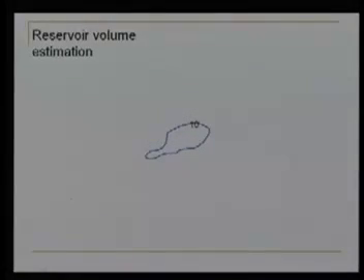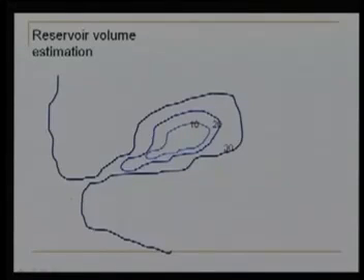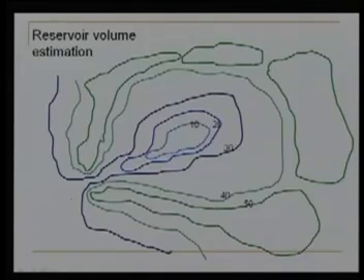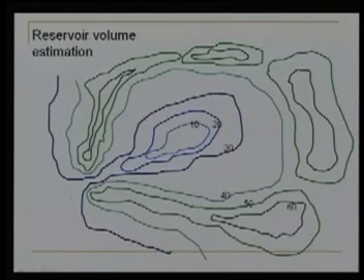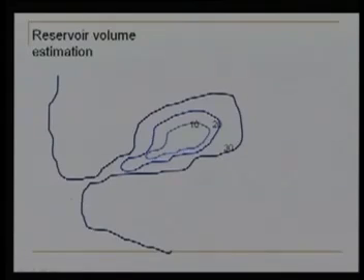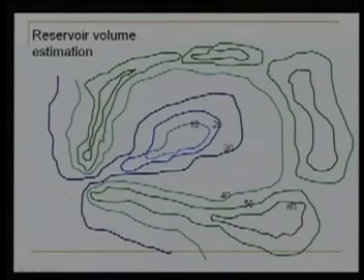Again, our area is similar to the previous case. Here we have the contours of 10 meter, 20 meter, 30 meter, then 40 meter, 50, and finally 60 meter. Now try to visualize this area the way we did with the contours before. Try to visualize what this area is like. This area is somewhat like a little valley, while it is opening here. Opening means over here, if I highlight that.